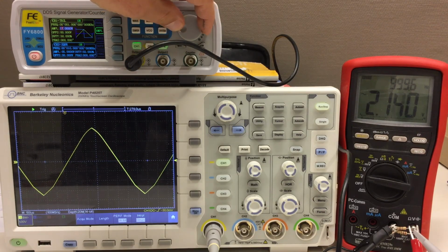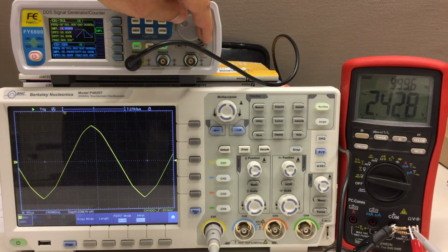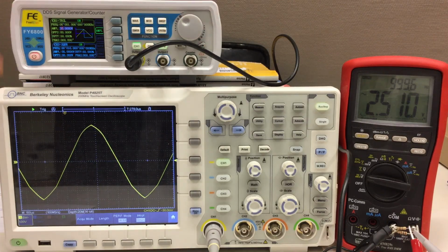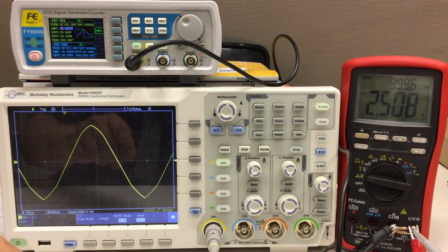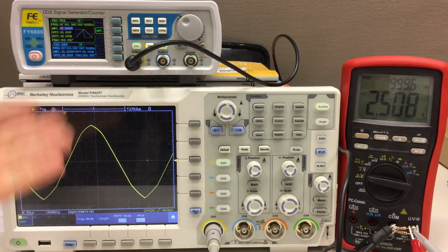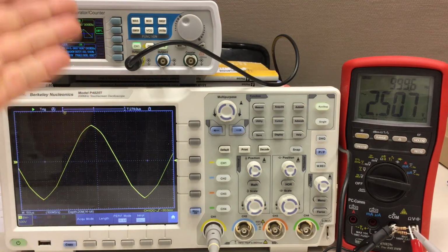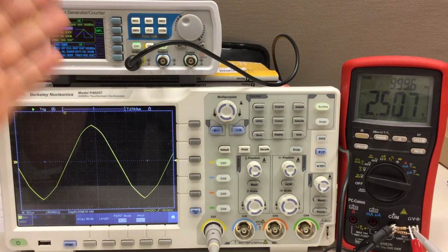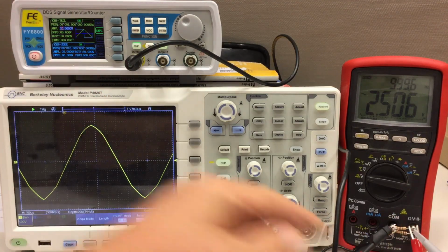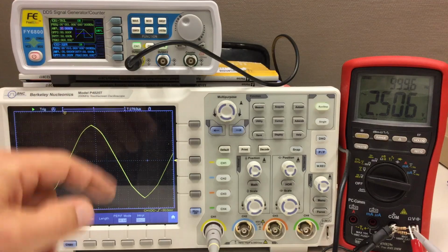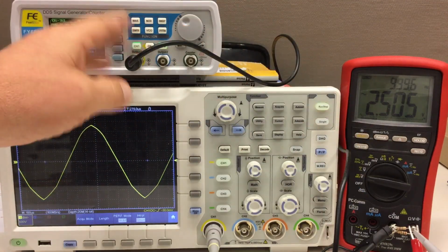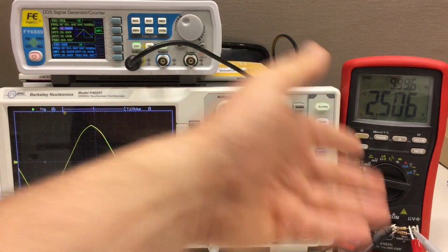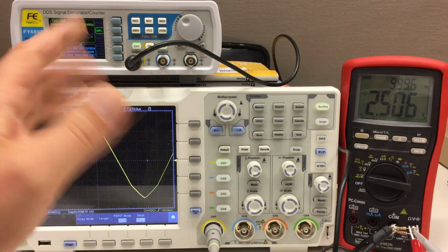Yeah, I think you can see it. Above 10 volts, my triangle doesn't look like a triangle anymore because, well, the unit cannot drive enough current for an external 49 ohm load, or a total resistance of 50 ohms nominal, 100 ohms.